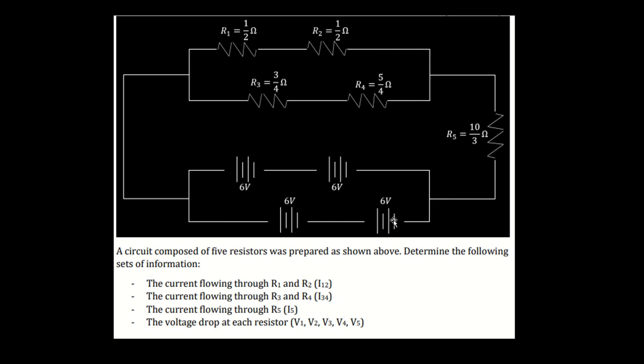That's the same as if we just had one single 12-volt battery. In other words, if you have parallel paths for batteries, we just need each path to add up to the same value, and then pretend we only have a single one of those. The reason being, if we had 12 total volts along one path and 10 total volts along the other, that higher voltage would try overcharging the lower voltage path and could essentially cause catastrophic breakdown for overcharging a power supply beyond what it's meant to hold.